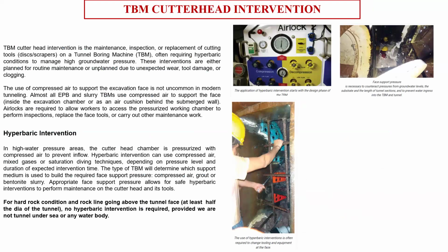It's a wedge method, where you assume there is a wedge ahead of the TBM face, a three-dimensional wedge, and you calculate the amount of thrust it applies. So it is a complex mechanism. It takes into account the ground shear strength. It takes into account your water condition, so that you can get a face pressure.